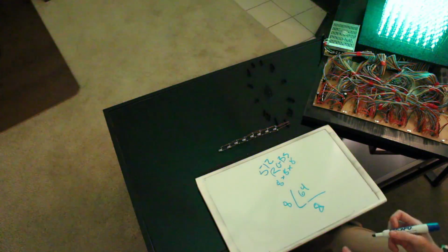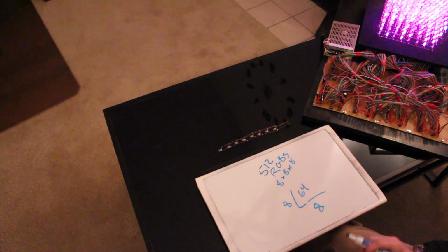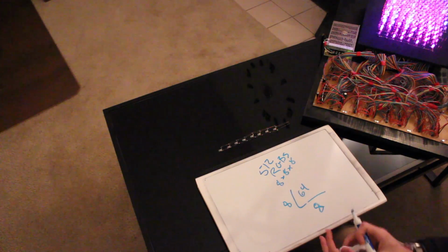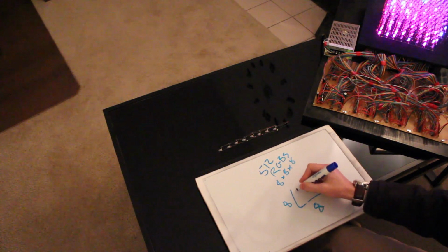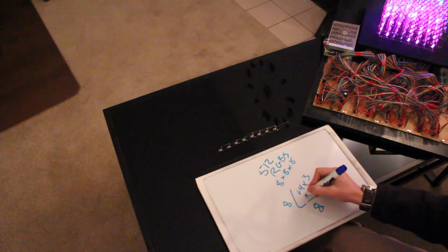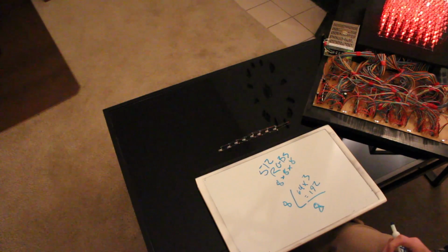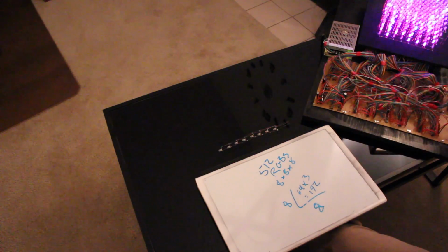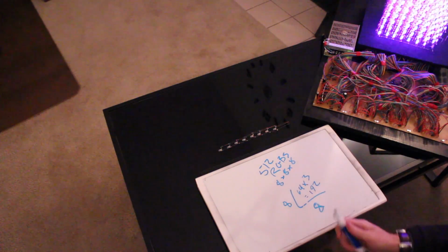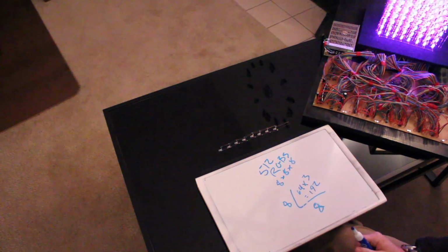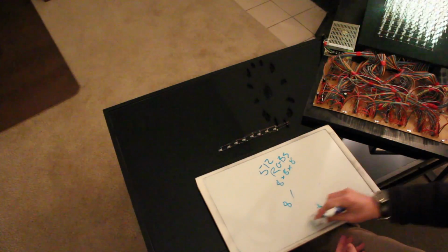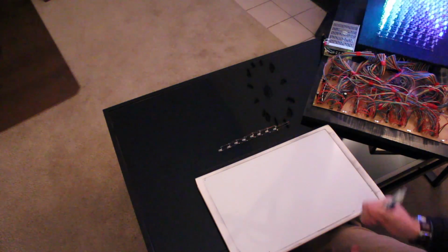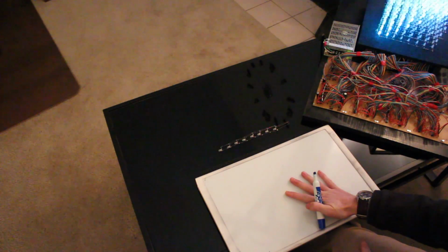So that gave us 64 pillars, and since there are 3 LEDs coming down, we have 64 times 3, which gives you 192. So there are 192 pins coming off of all these ribbon cables, and those are all the cathodes. These are common anode LEDs. So you have 192 cathodes.